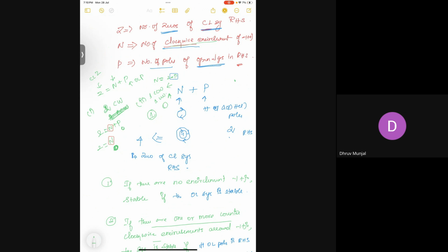These encirclements are of the open loop, and we are talking about the closed loop system. Even if in the open loop system one pole is in the right of the plane and one zero is in the left, since the Nyquist plot shows the effect is nullified, we say the closed loop system is stable. That's the essence of the Nyquist plot: with only the open loop, we can identify how the closed loop system behaves.